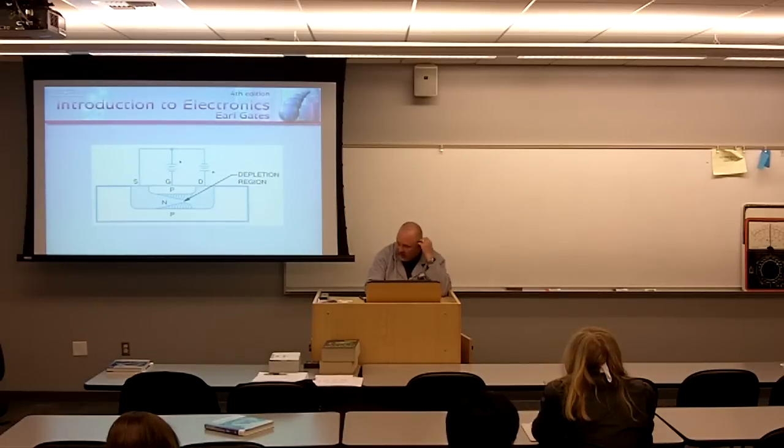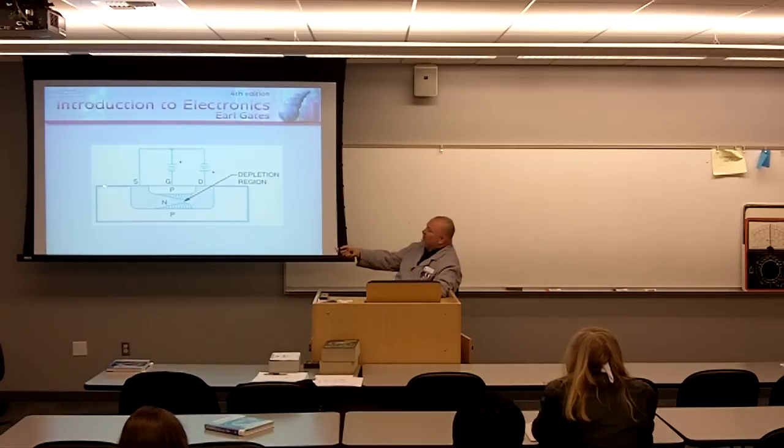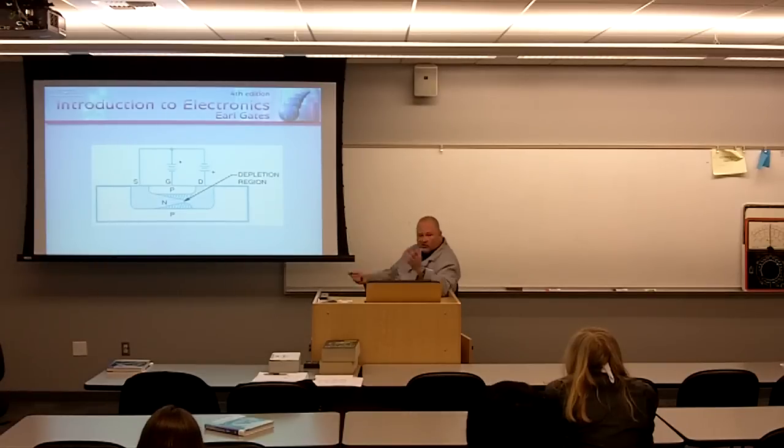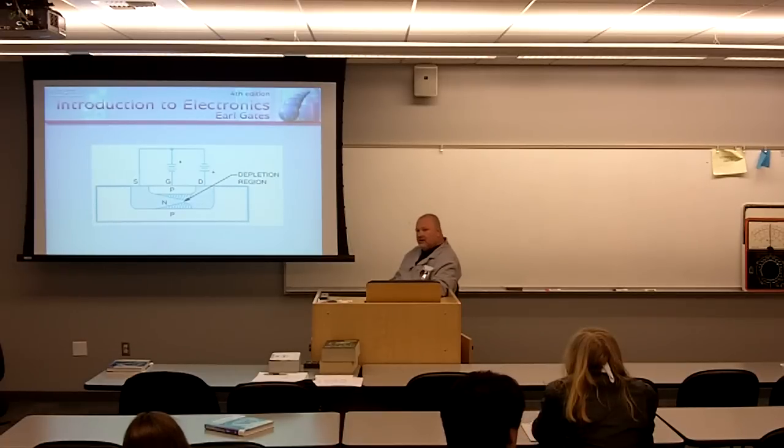And this is what one would look like, kind of sort of, as an artist's depiction. So this is an N channel. This is made on a P-type substrate. There's our P material, and then there's our N channel. So this would be like a channel, like the English Channel, that ships could pass through. Instead of ships, electrons are passing through. So this N channel is carved right out of the P-type substrate. Not carved out, typically probably diffused in using the photolithography process.